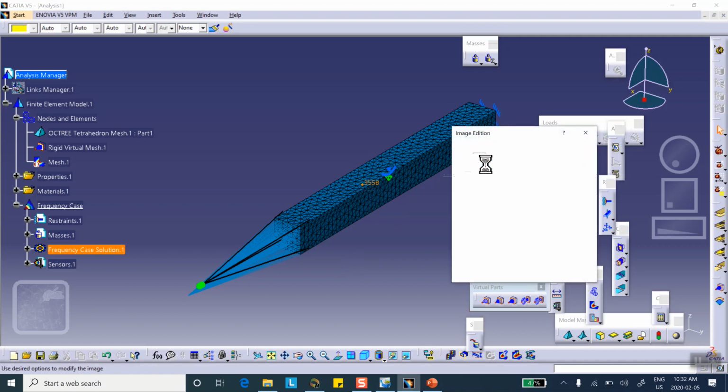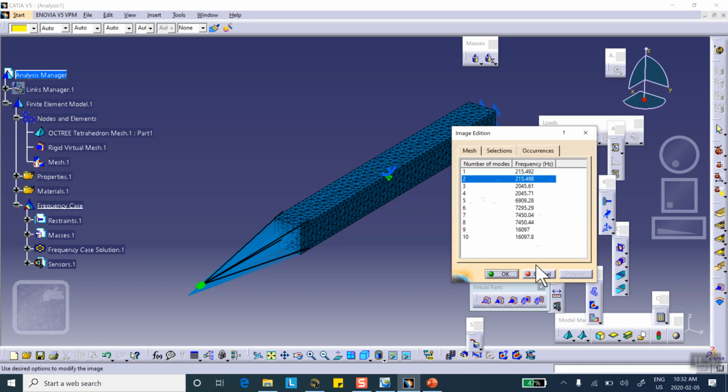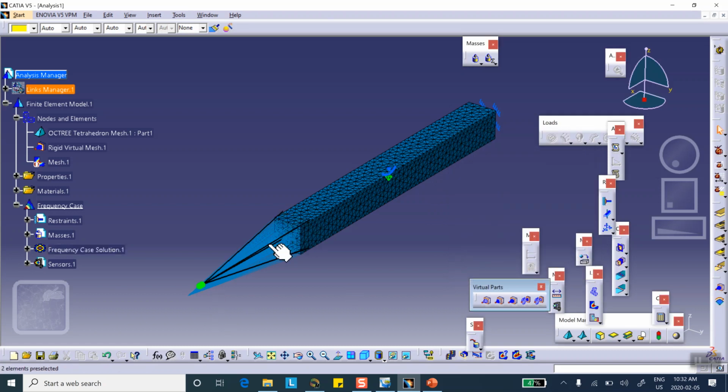So you can see the advantage of the virtual part is that I don't have to model this very rigid piece. Why would I do that? Because if it's rigid, it's not going to do anything. We created it as a virtual part. We did not create the part. We created a virtual part, and we placed the mass of that at the handler point.